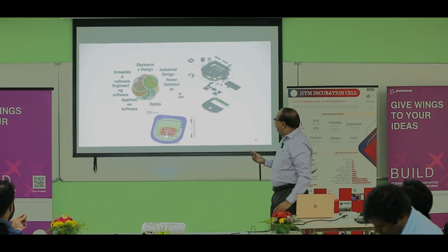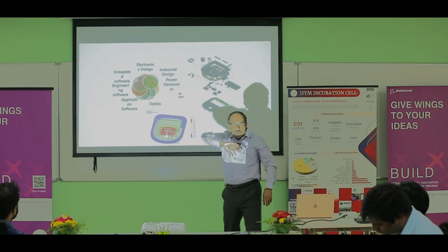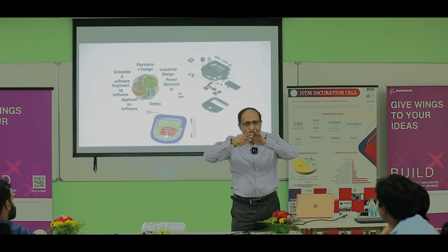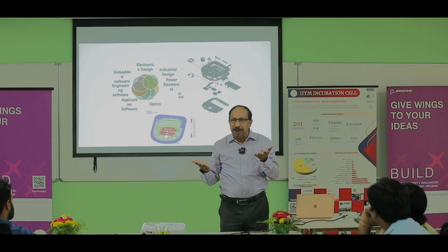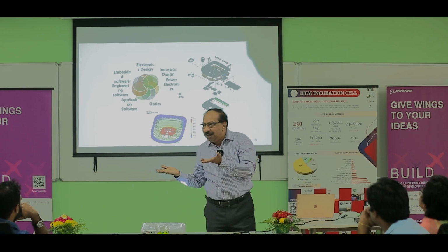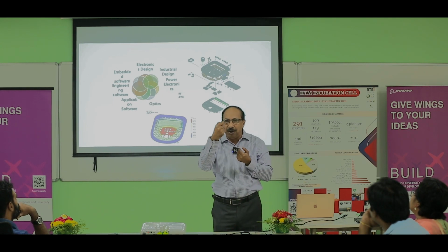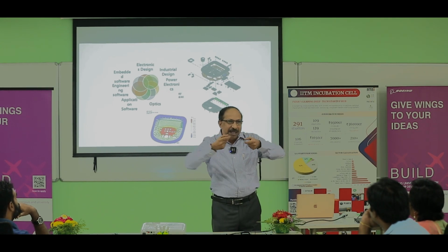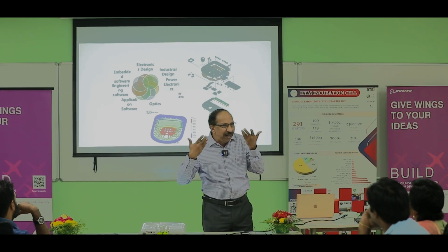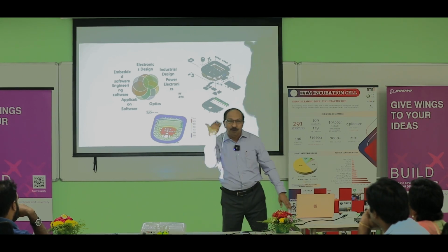So like that I did. Another thing is that the doctor or technician will be using the knob here, so he or she will be putting a lot of pressure there. When you put pressure, if the material can bend, it can create problems. So what you can do is increase the thickness of the material. Then the cost will go up, right? So what is the alternative? The alternative is you can put some ribs like that. Those who are mechanical will know. Instead of increasing the thickness of the material, you can put some ribs, which will strengthen that area. So you need not put a lot of material, just in the design itself you put a rib. That is how you have to think.